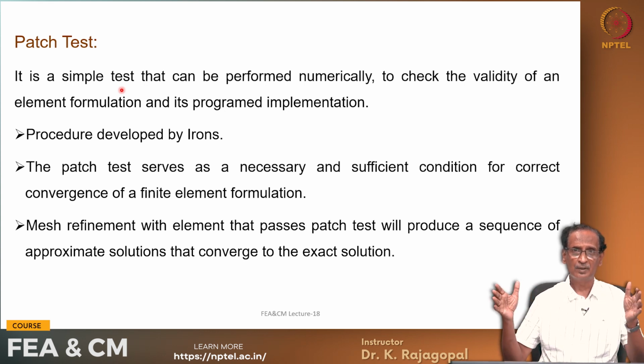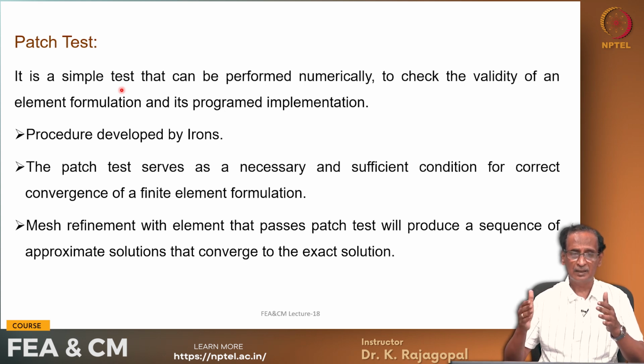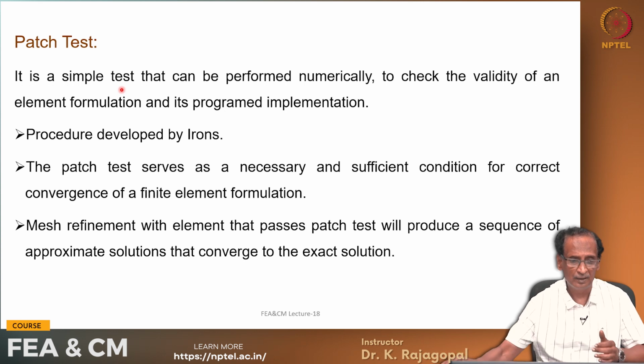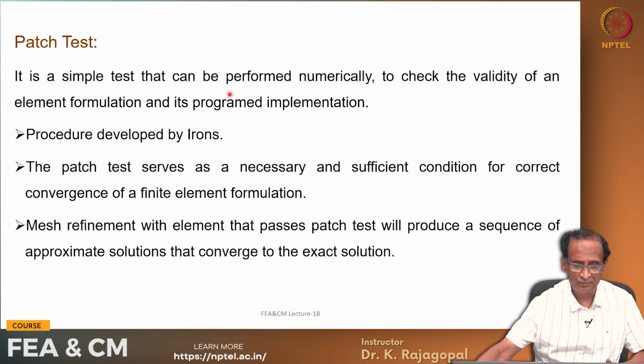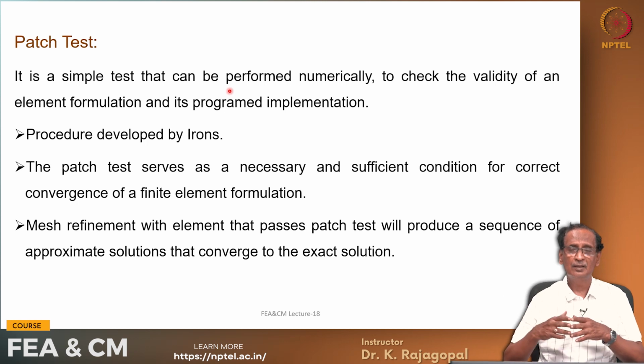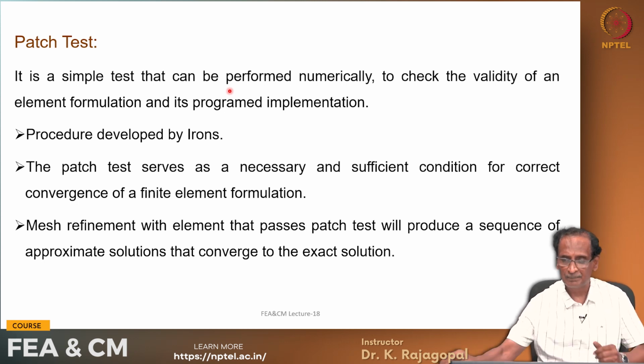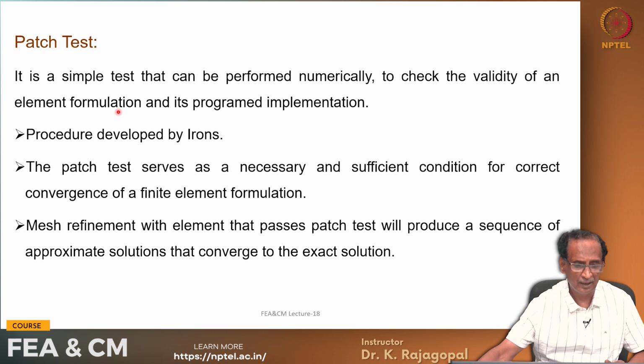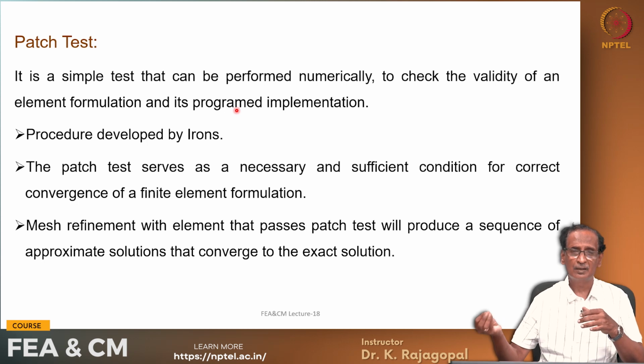Then if you subject an element to a constant strain state or constant stress state, we can predict the same thing within the element, and the same thing we are going to demonstrate numerically. And this particular one is done through the finite element programs, and this is to check the validity of an element formulation. And sometimes, see, the element may be correct, but we might have made some mistakes in the program, and by doing this we can verify whether the programming is also correct.